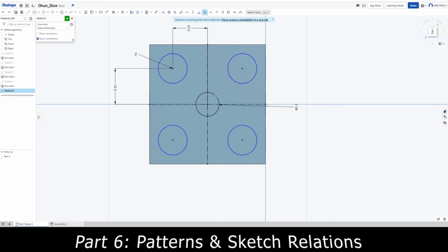So you're going to click equal, and then select this first circle. Then if you select all of them, they're just going to all change right there. Now usually you'll have to select every single circle, however, because this is 4 times of this one, so basically these 3 are a copy of this circle. So once you change one circle, every single circle changes, which is kind of nice in this example. So that's basically how you use both of those.